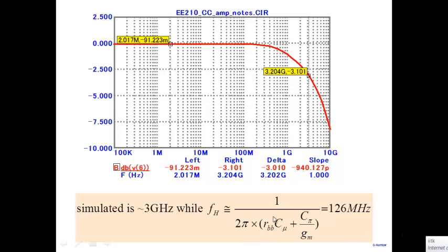So something is very drastically wrong with this. As I said, this is an approximation, an approximation based on a dominant pole. If you recall, we knew that there are poles and zeros in the transfer function. We assume a dominant pole, and on that basis we calculate. In most cases, the numbers that you get for common emitter, common base, and so on are fine. But in this case, common collector, it gives us a value which is way off.